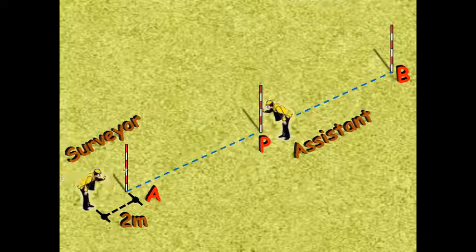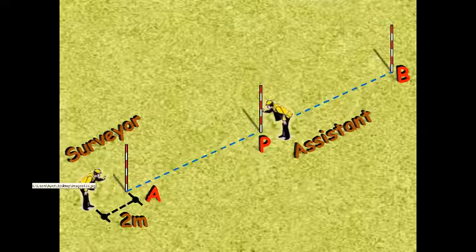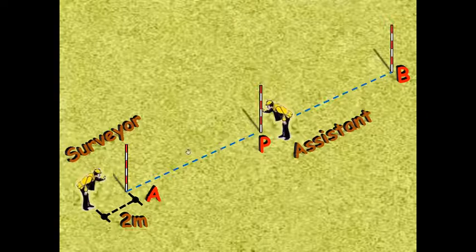So he can basically see just one ranging rod. That is when he would know that the three are in one line, and then you can fix this intermediate point. You can do this with the naked eye if you don't have any instrument, or if you have a theodolite or an auto level, an instrument that has a telescope and a bullseye, you can do this with much more accuracy.